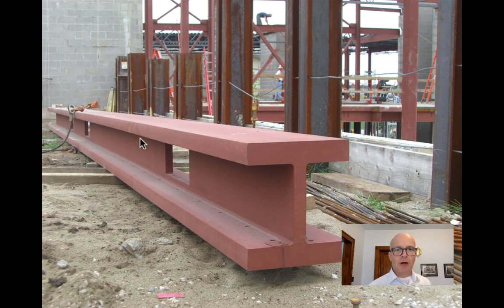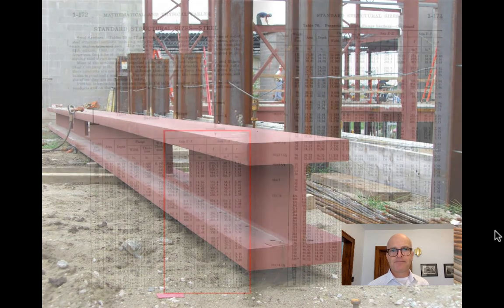Note too that we'll often find webs with penetrations in them, usually for mechanical systems, and that is another benefit of the W shape, that the web is basically lazy material. It's working in shear, and as we'll see, it's working not only in vertical shear, but also in horizontal shear, keeping the flanges together. But those stresses are typically much less than bending stresses, and they're much less than the tension and compression that those flanges are going to experience.